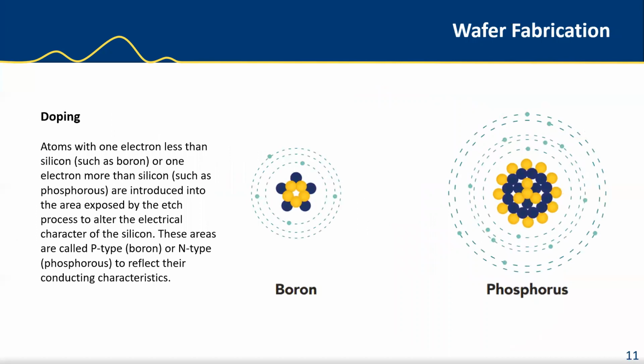The doping process is the introduction of impurities into the semiconductor crystal wafer to deliberately change its conductivity due to deficiency or excess of electrons. This process creates positive and negative areas on the wafer. Since silicon has 4 electrons in its outer orbital that can form perfect covalent bonds with 4 other atoms, the element can create a framework for crystal structures. Although this crystalline structure looks metallic, silicon crystals aren't metals. For this reason, only a tiny amount of electricity flows through it. However, all this can be dramatically changed by forming P and N-type semiconductors through the process of doping silicon.